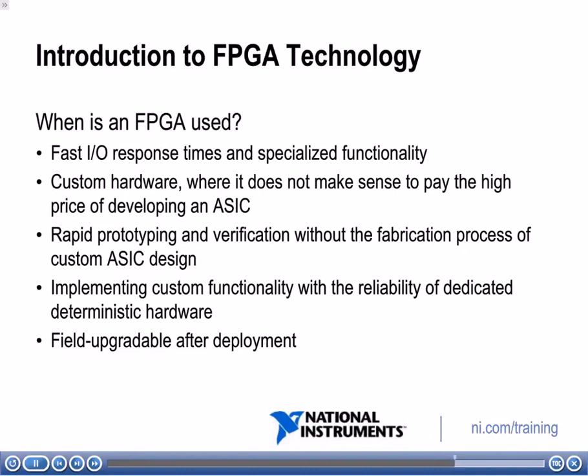Because an FPGA is implemented in hardware, it's going to be very reliable. Also, another thing that is really beneficial with FPGAs is that it's field upgradable after deployment. If you have an ASIC, once you've created it, you're not going to be able to change its functionality. However, with an FPGA, if you implement an FPGA with a certain algorithm on it, then later on, if you need to update that algorithm, you can take that FPGA and just reprogram it to have that new algorithm on your hardware.